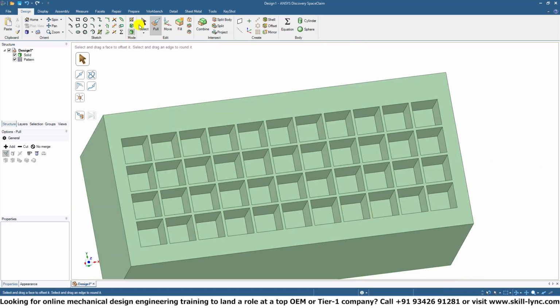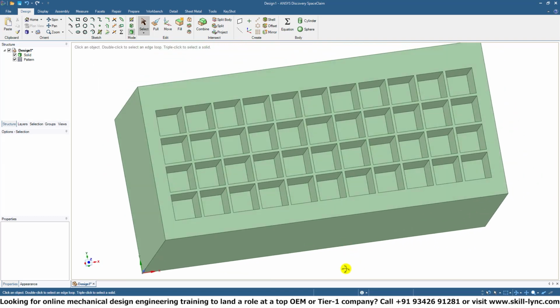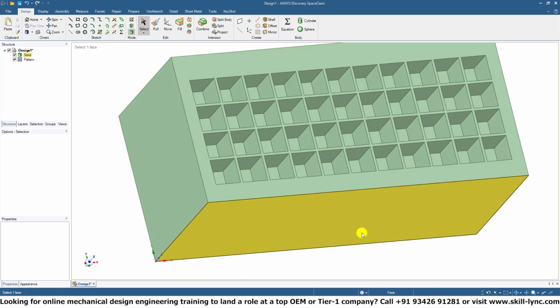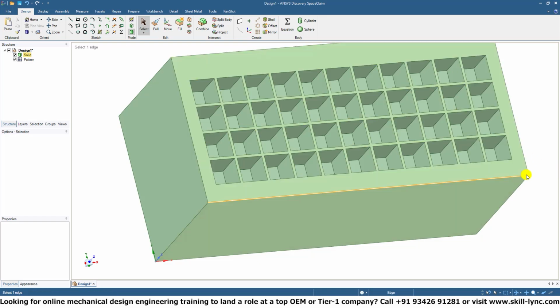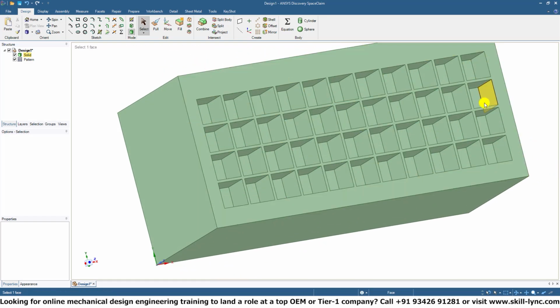But in essence, all you have to do is try the technique, and hope you get the results that you're looking for. If it doesn't work out well, you can always Control Z, undo the action that you just did. But you see, using that linear pattern, we could create quite a big ice box or ice tray, where actually drawing these out one by one by one by one would take a long amount of time.